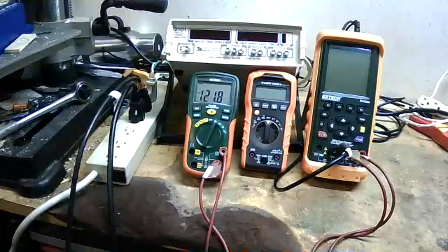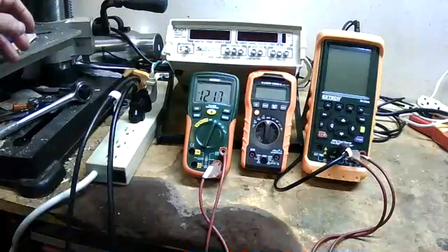As we go through these demonstrations, you'll see that varying. I've seen it vary from, I think, 118 to 125 as I've been working in here getting these set up. That's very common. The voltage on the power distribution system varies, and specifications usually are it can vary plus or minus 5%. And on a 120 volt system, that is 114 to 126 volts. So as long as we're in that range, we are getting the voltage that the distribution company guaranteed us.